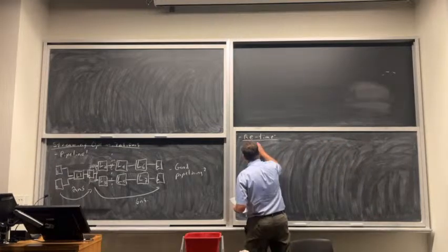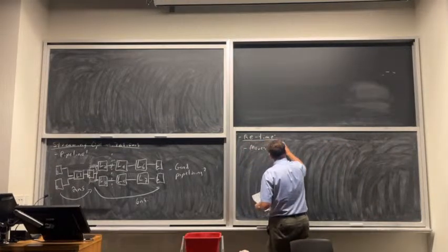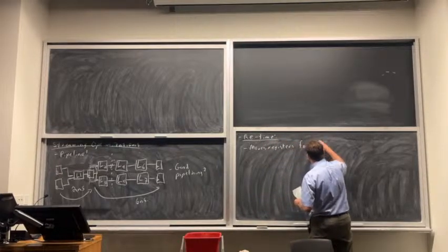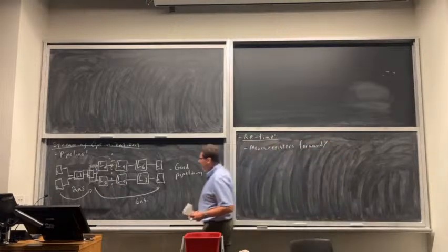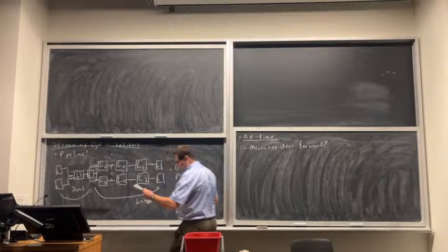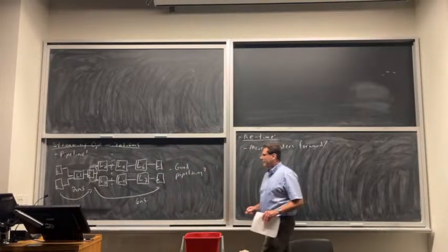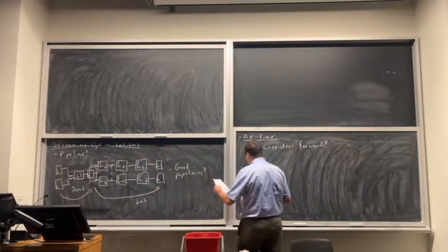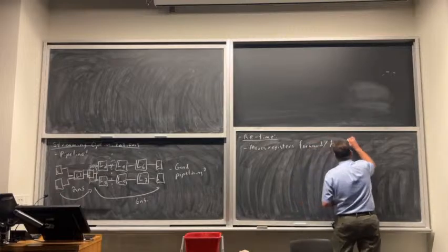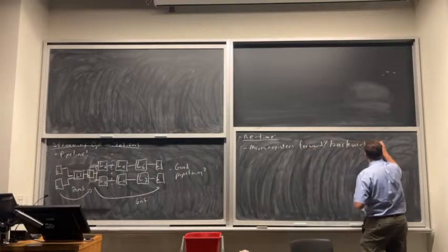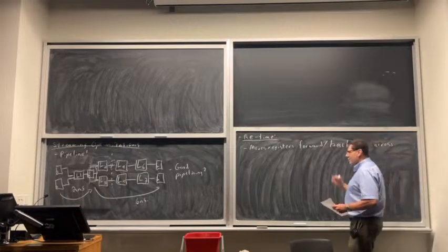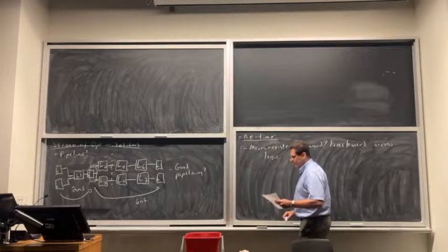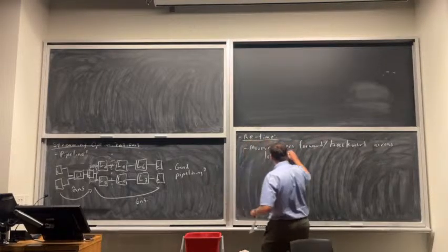Okay, so retiming moves registers forward. What I just talked about, the example I just gave you of moving registers from here to there, would be forward retiming. I'd move the register further down my logic. Okay, so I can move it forward. I could also move it backward. And this is not moving it physically on the chip. It's actually at the logical level. It moves it across logic. And the reason it's doing it is to balance timing paths.